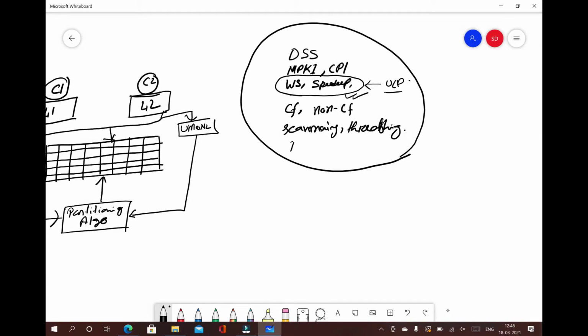One more important term is dead block. I hope you remember what a dead block is. I've explained it many times when I was explaining replacement policy, right? Dead block means, suppose there is a block here, and at any moment of time, if I point here, whether the block is dead or not depends on considering from this moment of time. If the block will not be accessed by any core before its eviction from the cache, then this block is called a dead block.